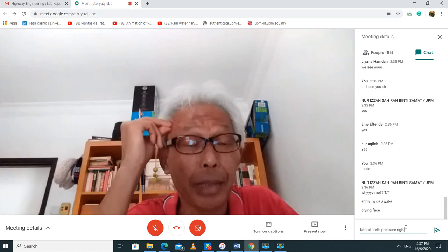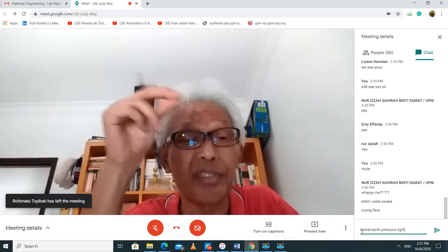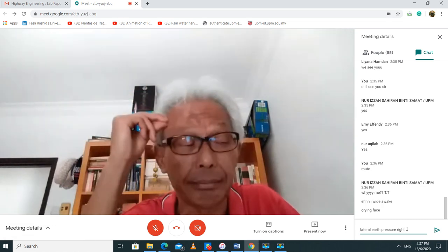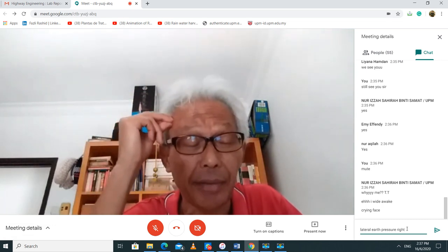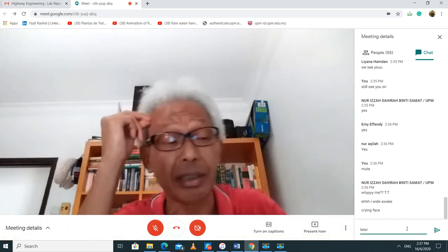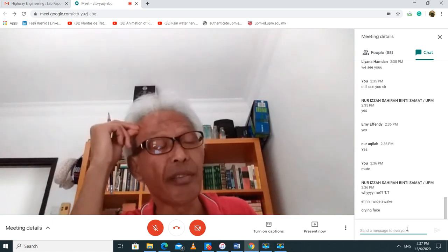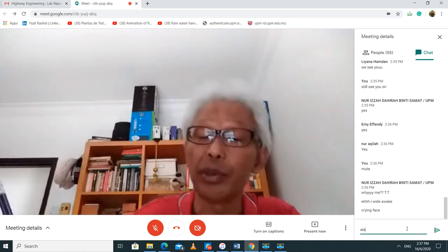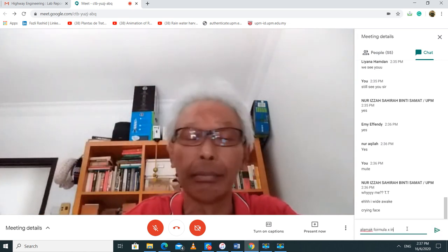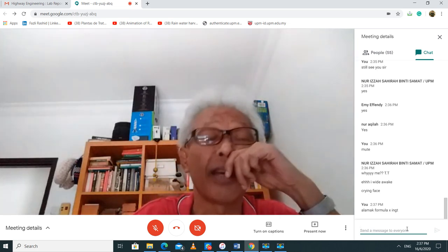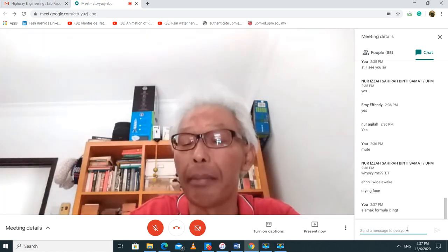This K naught is the coefficient at rest. It is in between K sub A and K sub P. Now, if I give you phi of 30 degrees, if you recall, what is the value of K sub A? If you don't recall, say, sir, we forgot. Fazli doesn't remember. Okay, the formula for active is 1 minus sine phi over 1 plus sine phi.